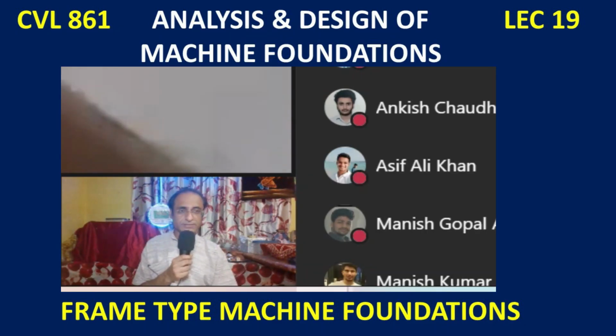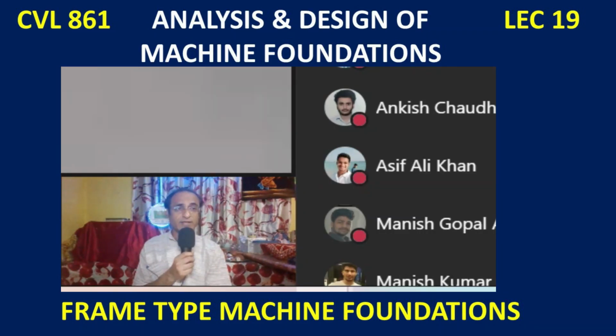Sir, another question is, if we do solid modeling, then what are the necessary checks we need to perform? In the case of a frame model, we can check the moments and shear. In plates, we check the stresses. This is a good question. If you are doing space frame analysis, the output will give you all the shear forces, bending moments, axial forces. But if you are using solid modeling, you will not get these directly.